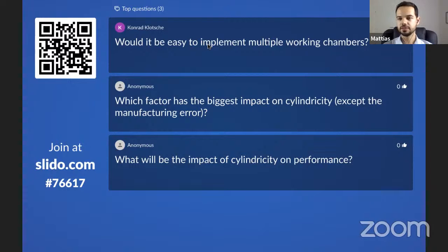For a certain clearance, you would have a distribution around it that could facilitate having more leakage or not. On the other extreme, if you are decreasing the clearance too much, we start having asperity contacts, and that could also influence performance by increasing friction. So we have these two main kinds of effects, but it's really an experimental evaluation to see how it will influence.